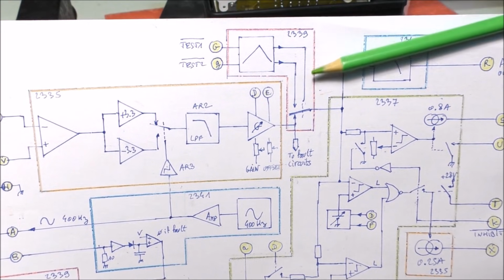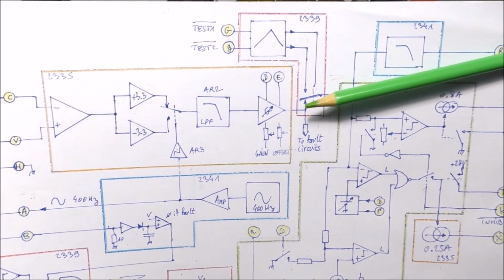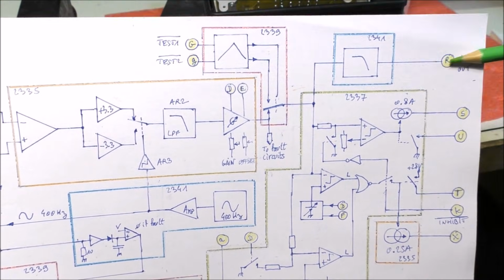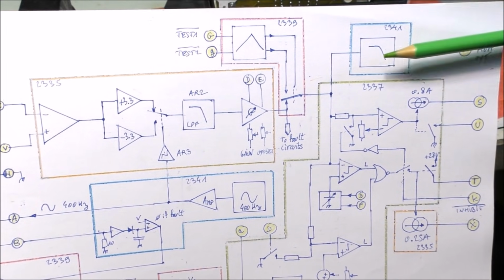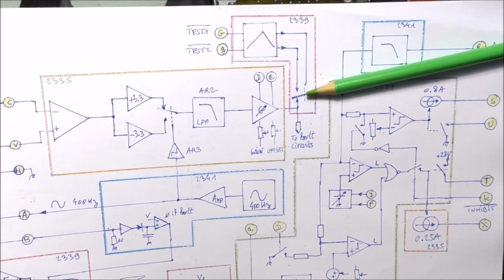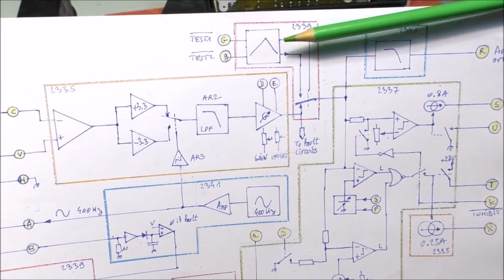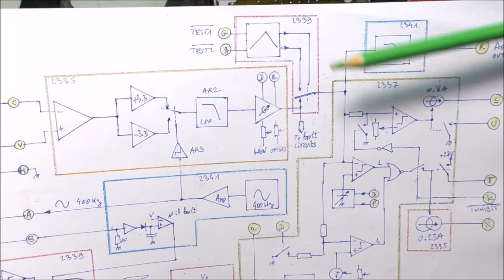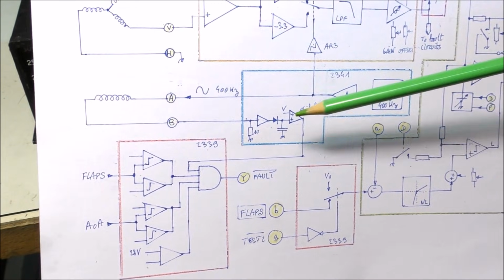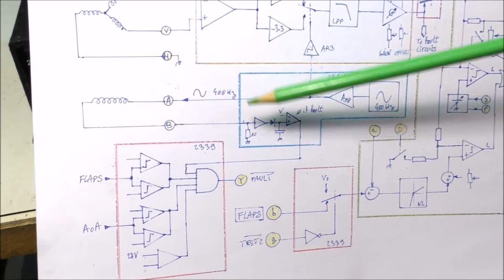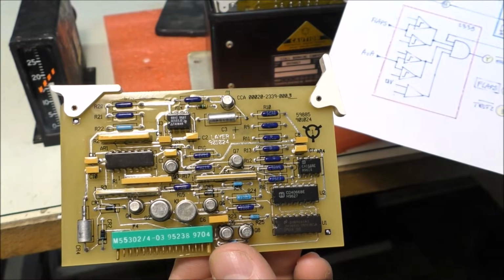And here this is the second board, so this permits to activate a kind of test. There is a relay here. This is the output of the angle of attack. We have already seen this voltage follower on the first board, and we can see that we can select between the angle of attack and a ramp which is given by this board, 2339. There is also a detection of a fault. The first fault corresponds to an open synchro here. So this is the function of this board. It's a kind of error board.